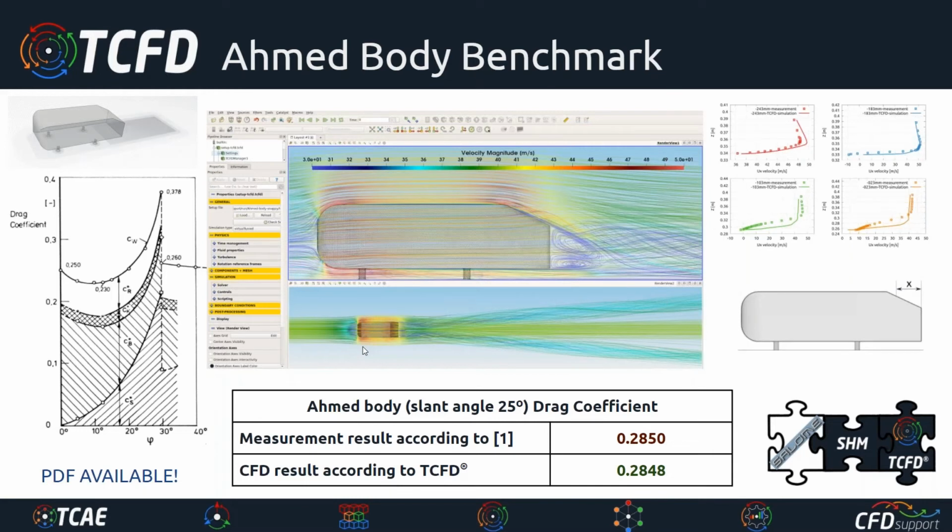Yeah, Ahmed body. This is a classical study that presents the benchmark validation of CFD simulation of this famous external aerodynamics test case, which is called the Ahmed body. We did the simulation using TCFD. Ahmed body, as you know, is a generic car body. It's basically a simplified car model, and the flow of the air around the Ahmed body captures all the essential flow features around an automobile.